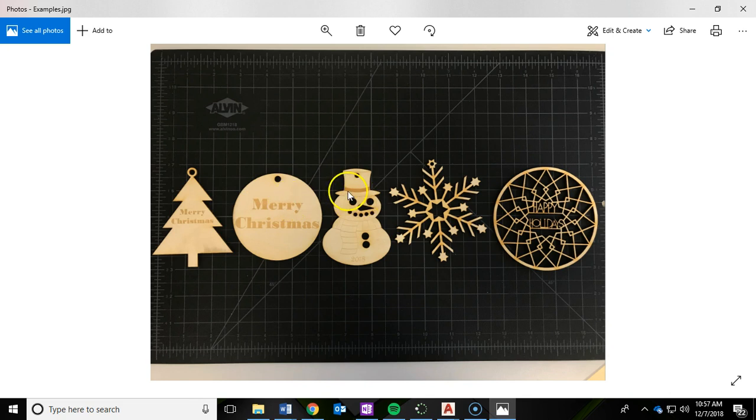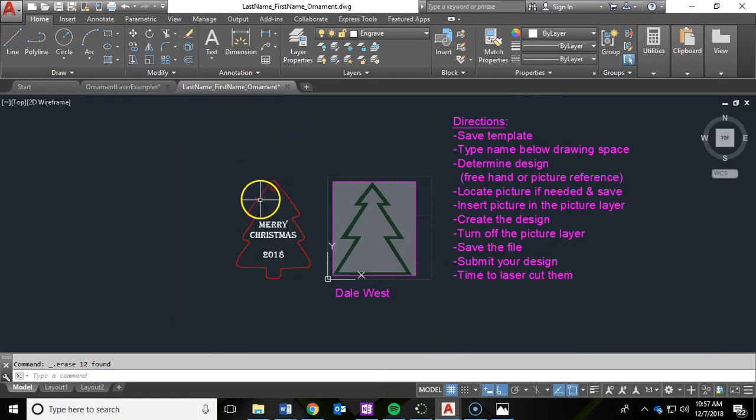Now you could also draw portions of engraving. It doesn't always have to be the text. You could have this part of the snowman engraved, and then the scarf is engraved, and then the text as well. Versus again the cut, they drew for the little buttons here, as well as the mouth, the nose, the eyes. So that is engraving versus cutting on the laser. So you're going to have to determine, what do you want cut out and what do you want engraved.